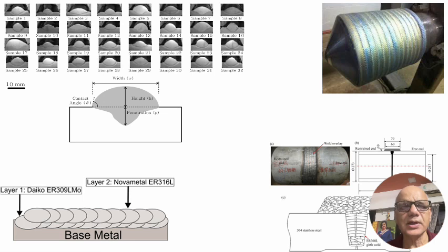So I hope that you are enjoying this type of welding also, and understanding the features which are required to be done. So I will repeat again that the angle, the depth, now this kind of a penetration is not acceptable in overlay. We must get the flat as I showed you in the earlier slide. Width should be as maximum we can get it using diameter into maximum 2 times, or if it is submerged arc, depending upon the voltage arc length we are choosing, it can come to that extent. And this is the way we should start developing our welding techniques.